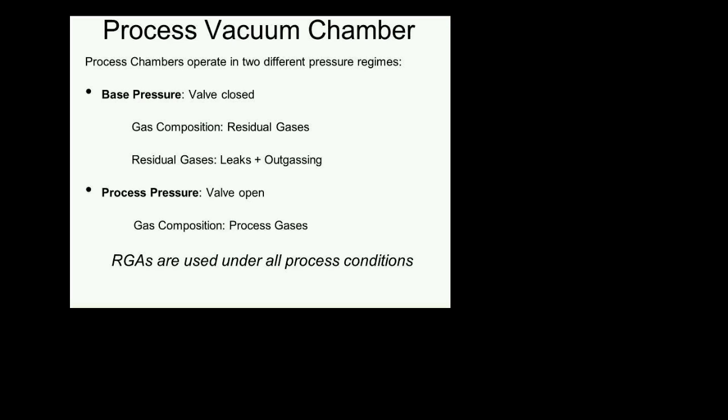Base pressure is when the valve is closed. You have been pumping on the vacuum chamber for a long period of time, you're not adding any gas to it, and what's left in that vacuum system is simply whatever is leaking in or whatever is outgassing into the chamber, and those gases are called residual gases. And this is why these partial pressure analyzers are often called residual gas analyzers,